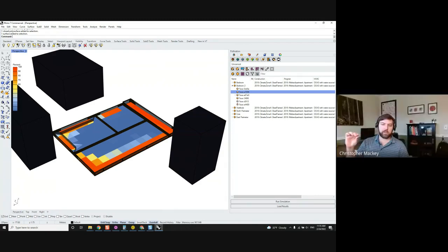Maybe we could say there are a few very high-level parameters that are exposed, things like the effectiveness of heat recovery or demand-controlled ventilation. There's a simple switch for that. A lot of things related to ventilation, you can toggle on and off. But if you want to get down into detailed performance curves and stuff like that, you'd have to go over to an OSM or use an OpenStudio measure to tweak those performance curves.